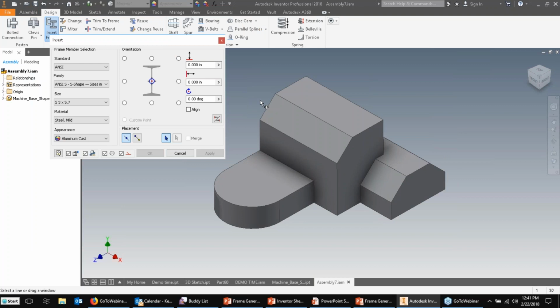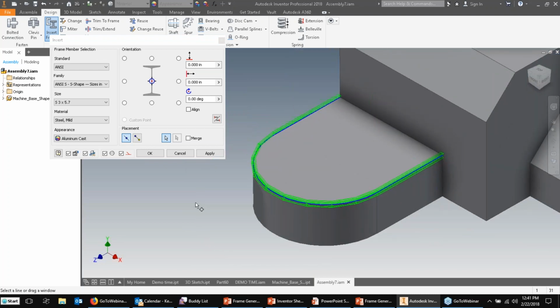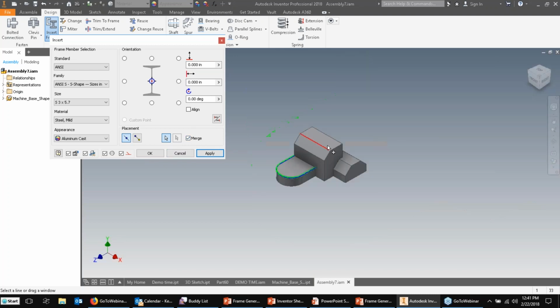When you're working in a situation like this, you've got the ability to make rounded corners. It will round that beam. Whether you can bend it like that or not is another story, but it will round that beam for you, and you can also merge those pieces into one. Without that, it's going to break it up into 3 individual pieces. But with the merge enabled, it's going to be one continuous piece that it assumes you're going to bend out in the shop to match it up.